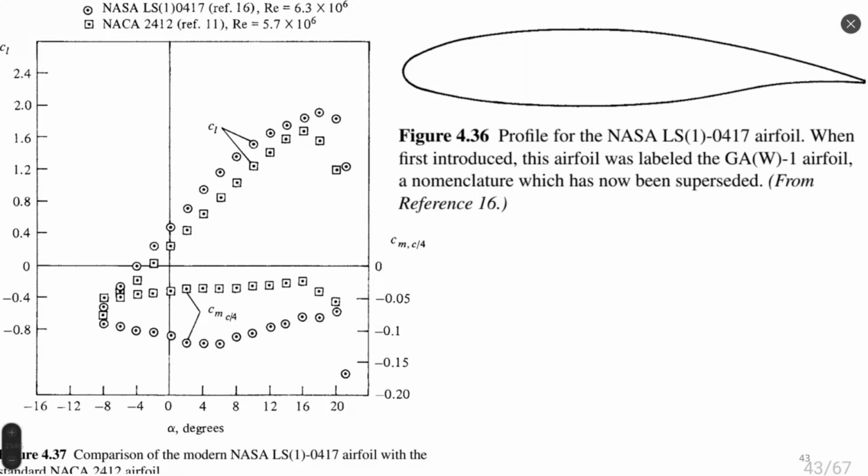So low velocity, high efficiency airfoils are made by numerical optimization of existing airfoils. As a base, we use an airfoil which works well, and we would like to improve it, starting to modify its geometry for different conditions, for different angles of attack, for different Reynolds numbers, for different Mach numbers. With a change of geometry, the airfoil can start working better or worse, like the lift to drag ratio will be higher or lower.